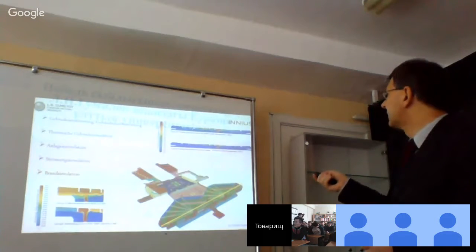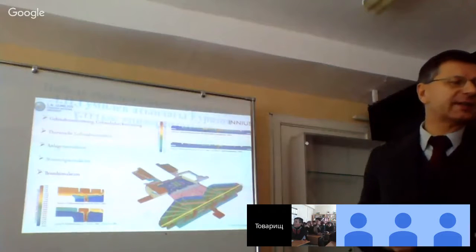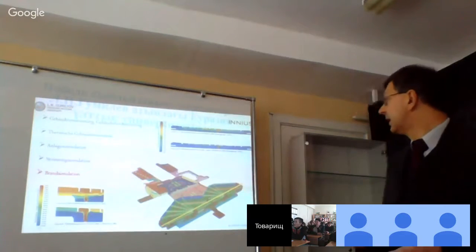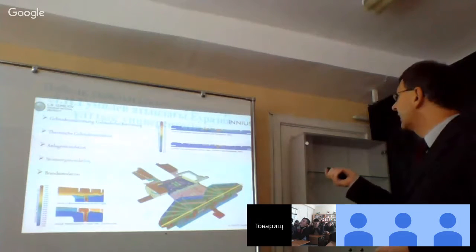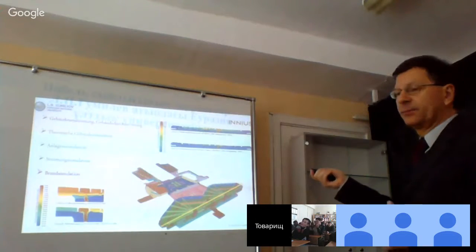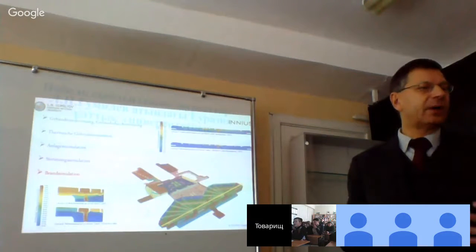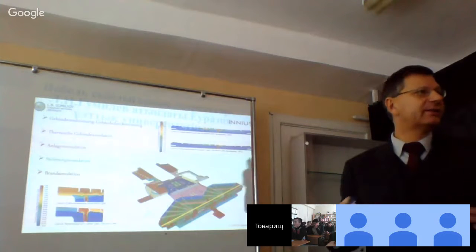In the upper case, you have an air quantity for the smoke extraction system of 400,000 cubic meters per hour, and in the lower part, 200,000. What you have to compare is that dark blue is the only part where you have no smoke. Everything that is not dark blue is smoke.